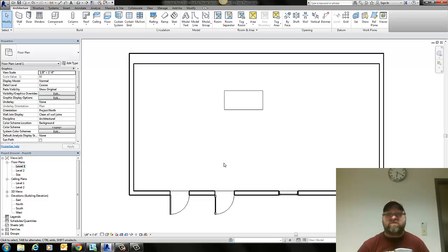So you always want to, before you start modeling, the first step that you should take is writing down exactly what you want to change. So, I'm going to change the height and the width of the door, and make it so I can change the frame as well, the size of the frame, or the material of the frame, or the style of the frame.